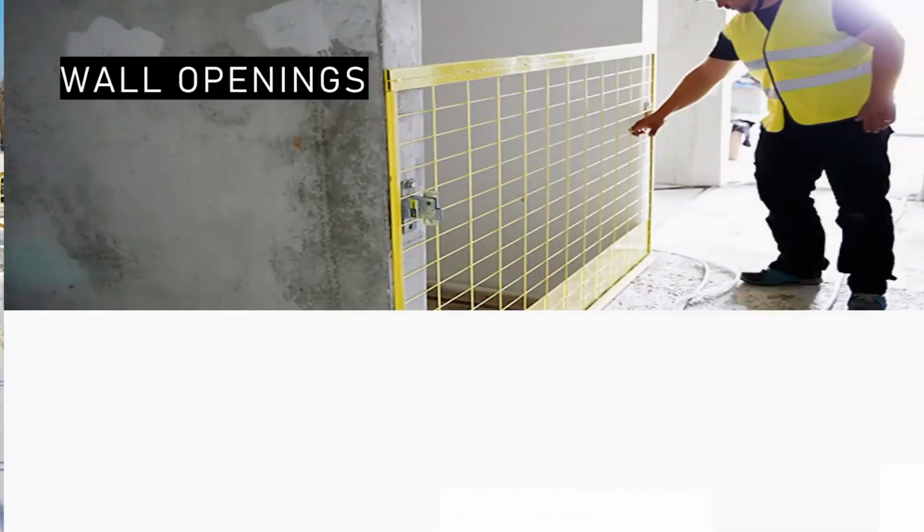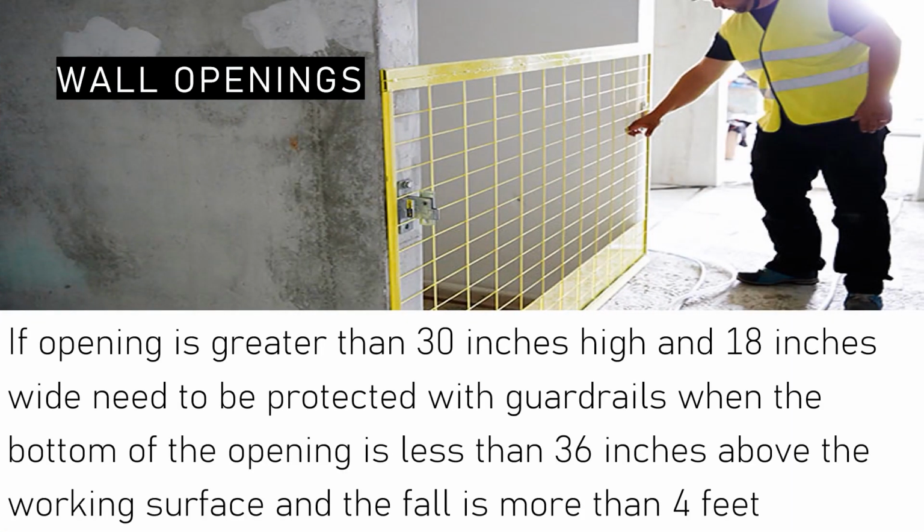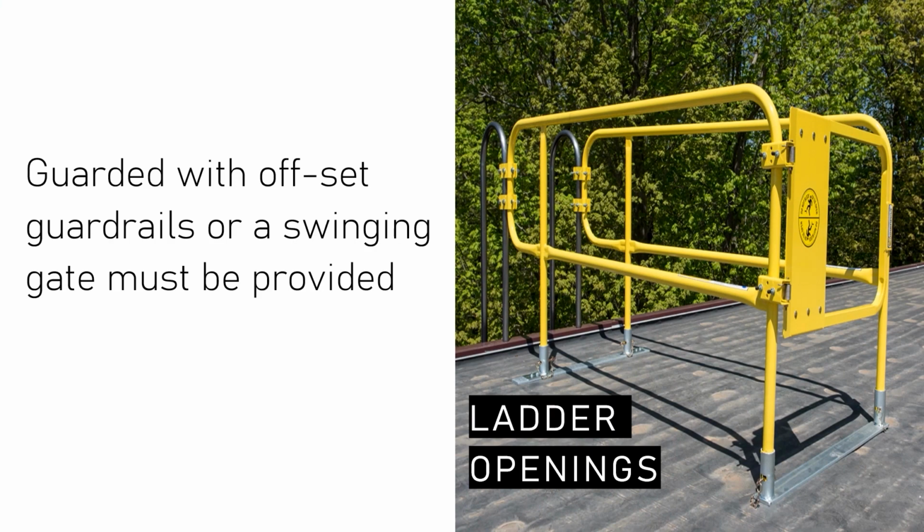Wall openings that are greater than 30 inches high and 18 inches wide need to be protected with guardrails when the bottom of the opening is less than 36 inches above the working surface and the fall is more than 4 feet. Ladder openings need to be guarded with offset guardrails or a swinging gate must be provided.